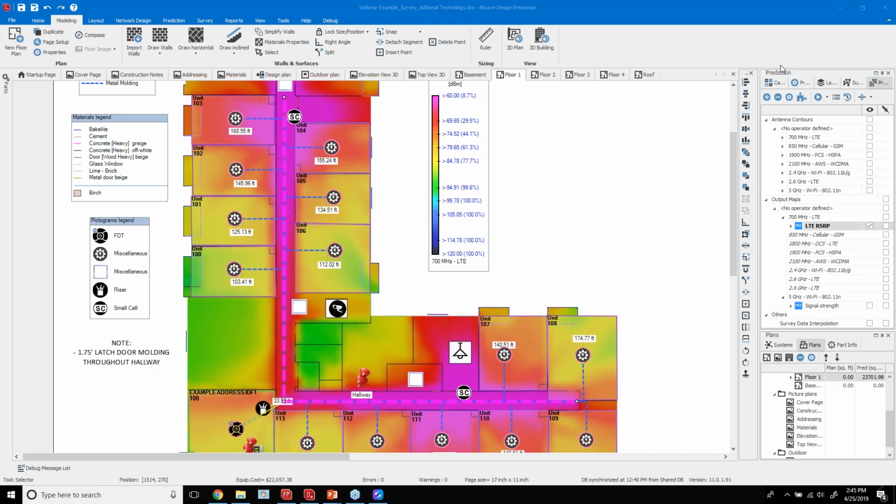Your single mode fiber has both transmit and receive capabilities, so it's working in both directions at the same time. So it's one fiber per unit for GPON application on the distribution side. And then when you get into the feed, your requirement really is only based on the ratio 1 to 32. Certainly smart to upsize your feeder though.